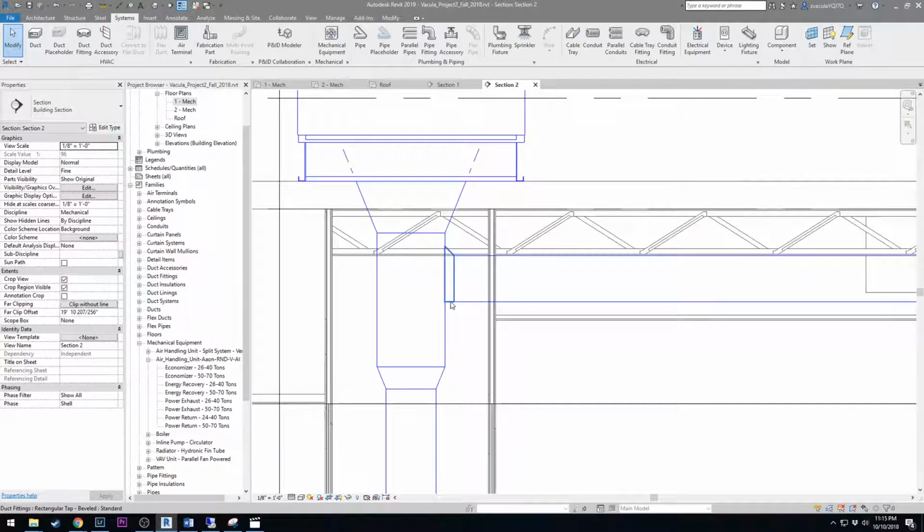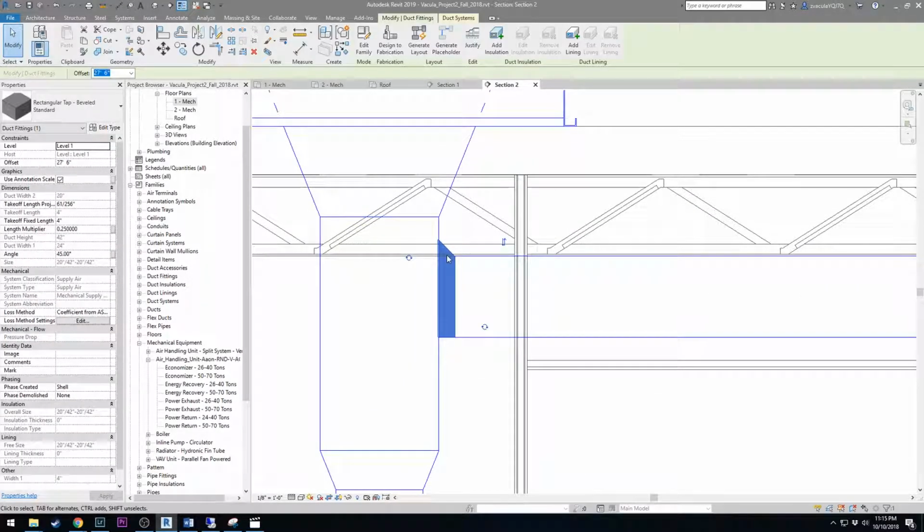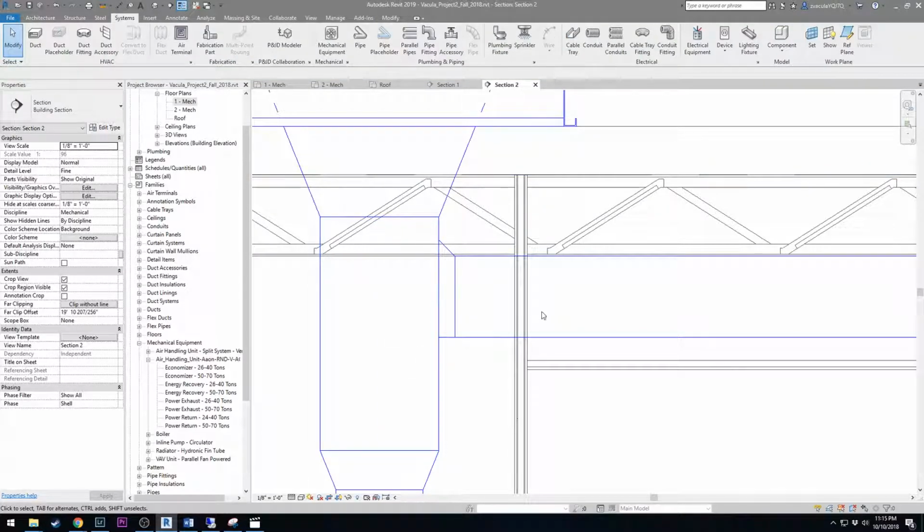And another thing is you want to make sure your bevels, or sorry, your miters here, these are always angled basically with the airflow. So air will be coming out of the unit and flowing and coming on this corner. So this helps reduce the drag or the pressure. If it was just a hard 90, it would not flow as well.